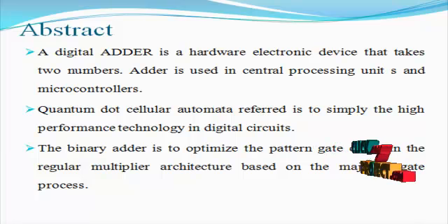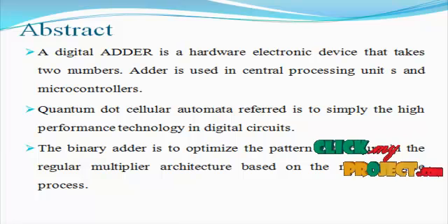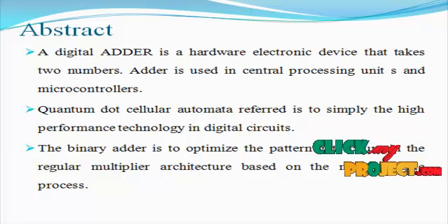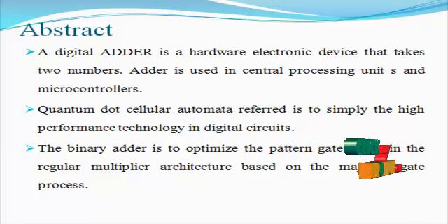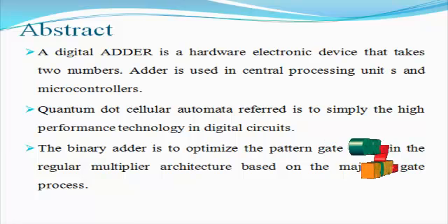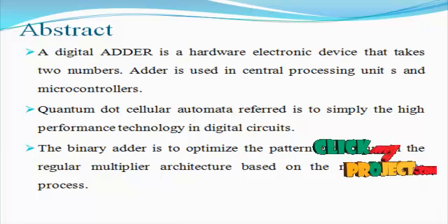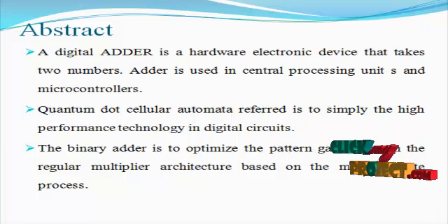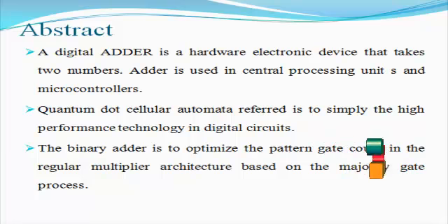Low power has become an important factor in modern VLSI design. The limited power capacity of systems has given rise to more power-aware designs by designers. Nowadays, power has become a more crucial factor than area or speed. However, different implementation technologies present different power optimization opportunities. Low power digital multiplier design based on the bypassing technique is mainly used to reduce the switching power dissipation.